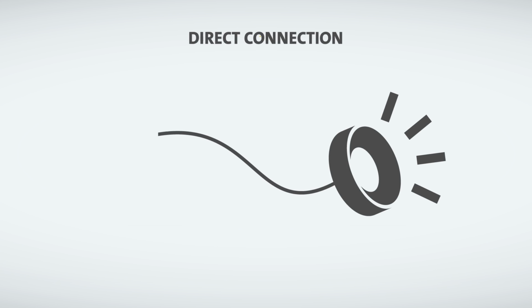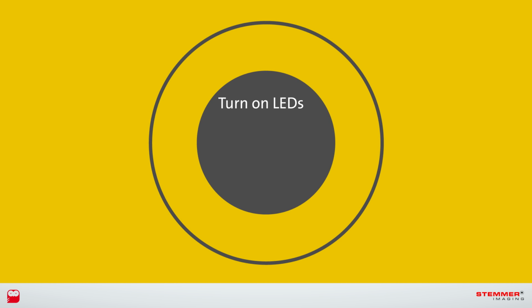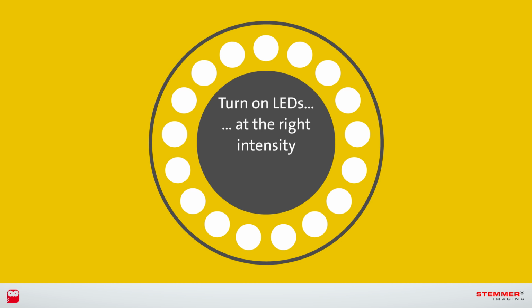Connecting the light to a power supply and having it run continuously may seem like the cheapest option, but it really isn't. It'll generate a lot of heat, aging the LEDs, and degrading any other heat-susceptible components within the light a lot quicker. To maximise the lifetime of a light, it makes sense to have it on at the brightness required, only when you need it.